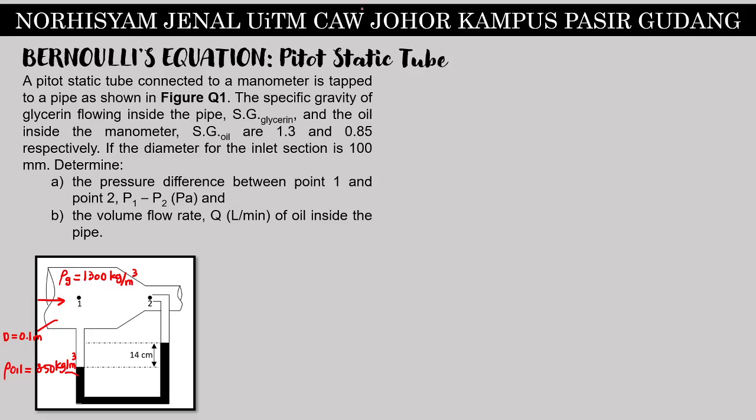Okay, if you see a question that is based on the idea of pitot-static tube connected to manometer, this part of the question should be on Bernoulli equation. This part of the equation should be on manometer. And remember the purpose of a manometer is to find delta P or the pressure difference. To start off, so what should we do? First, based on the information that you have, we go on and do the Bernoulli equation in terms of pressure because it is based on pitot-static tube.